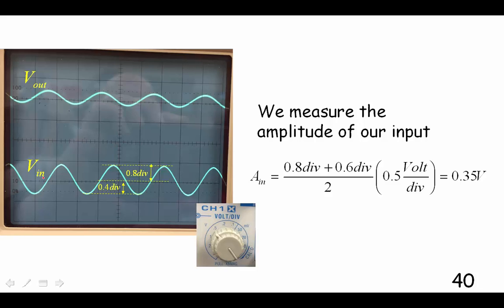Okay, let's measure the input and output voltages. Unfortunately, throughout this video, I never centered my waves, so the center line is a little bit off. So we are going to measure from this center line in every case up to the top and then to the bottom, and then we add the two and divide by 2, and we'll get the average amplitude. That's how we'll be doing it through the whole thing. And that happens commonly when we do our experiments. Sometimes it's not perfectly oriented.